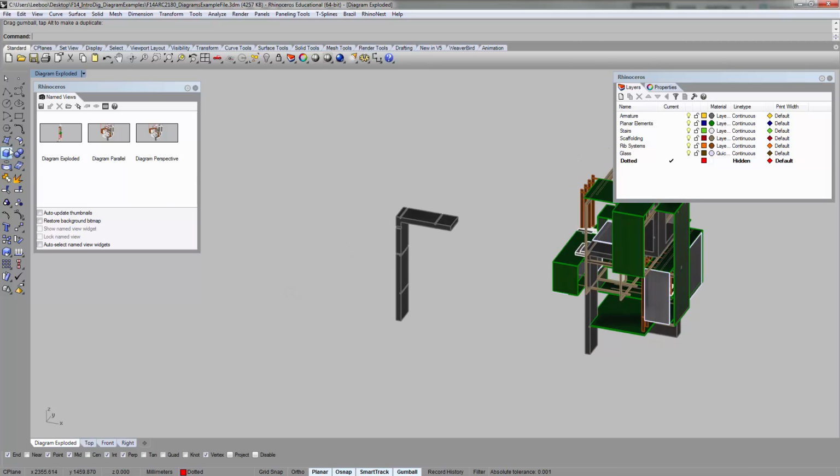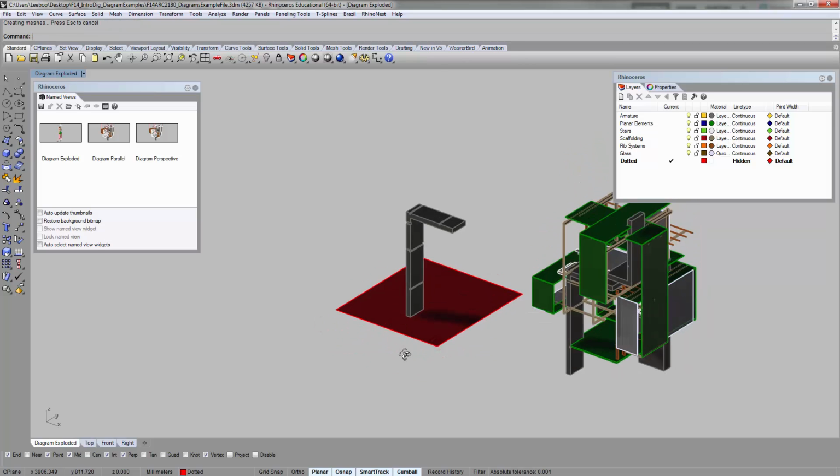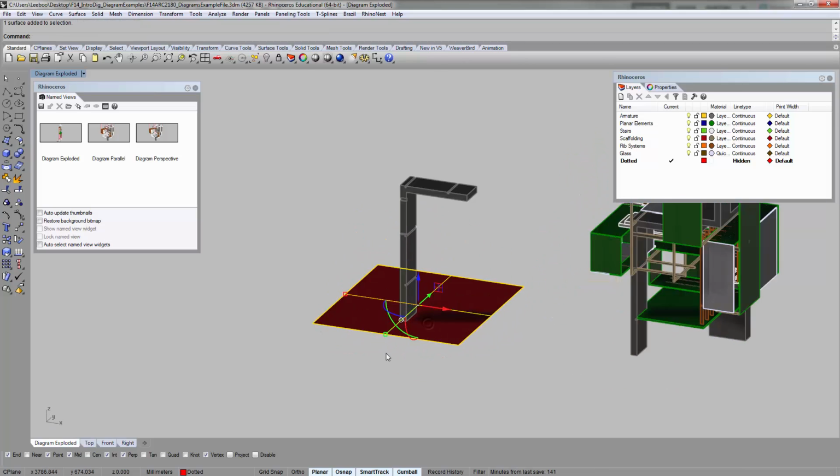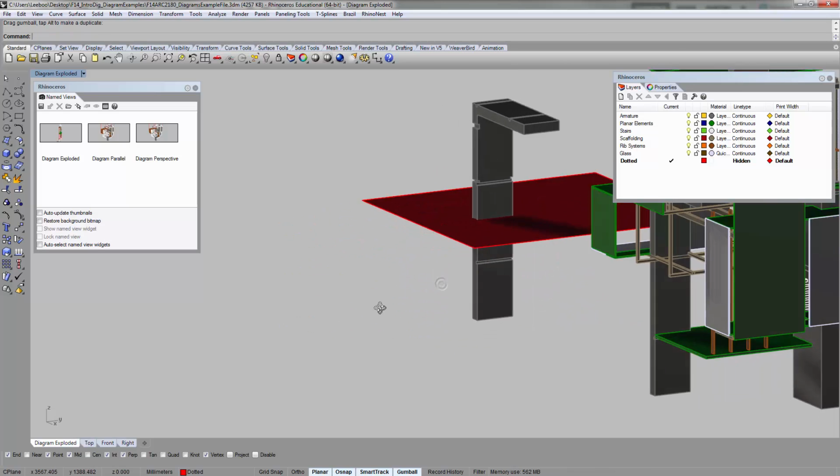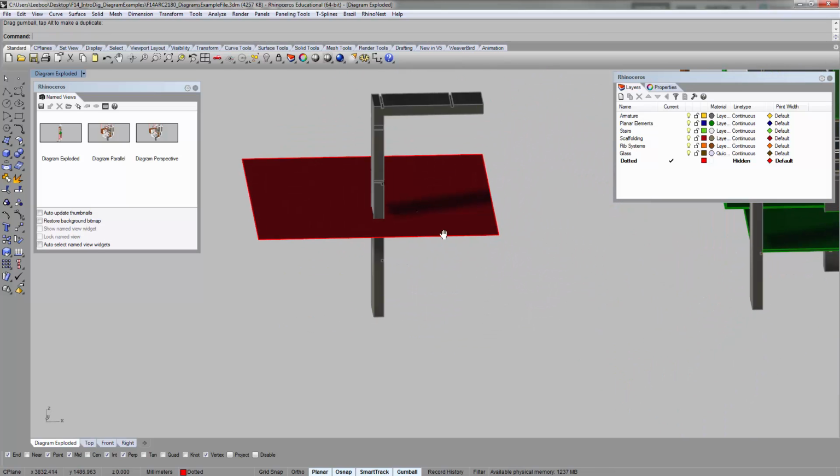I'm going to use here is the plane tool, the rectangular plane tool. The sort of Rhino command for it is just plane, P-L-A-N-E. And once you activate it, you basically draw a plane like this. You click, draw a plane. And what you want to do is move it somewhere up so it intersects with what you're cutting, right?